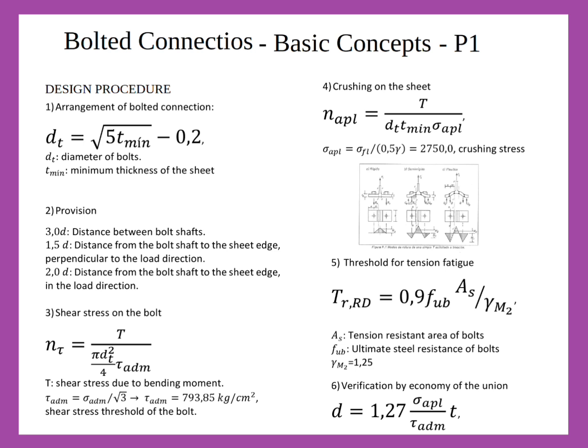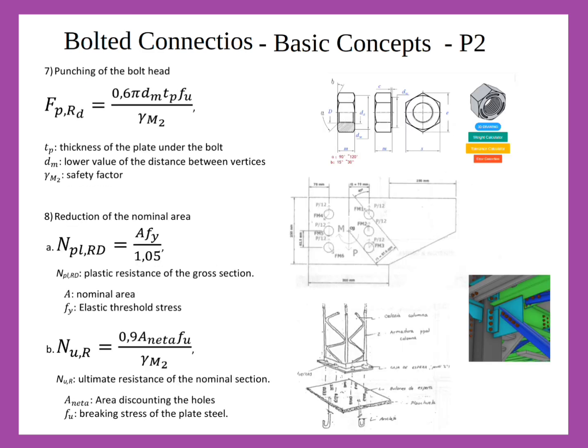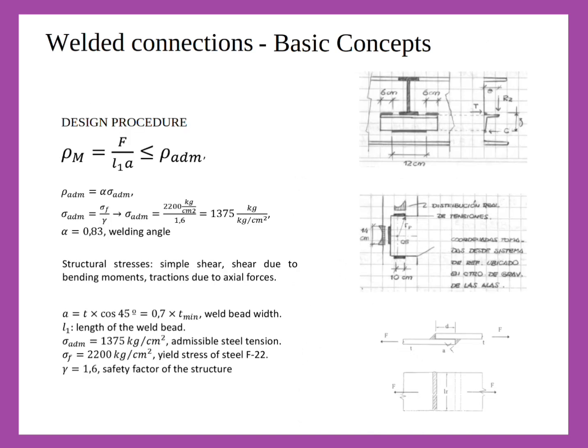Design procedure. First, the load values are extracted from SAP2000 for the worst case scenario, i.e., the maximum components of the stress envelope are selected. The worst case scenario is not necessarily when a load is at its maximum. When several load cases are present, all load combinations must be considered, since the combined effects of several smaller loads can be the most damaging. Then, the person performing the analysis will determine the transfer force based on the forces obtained with the software.